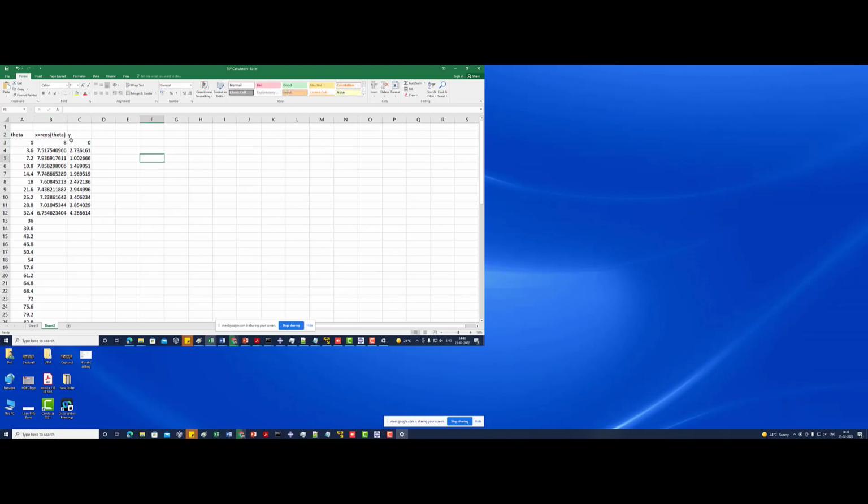So we will get the coordinates where we have to apply the boundary conditions, and then we have to calculate the values of u and v, which are the displacement in x direction and displacement in y direction. So this is simply going to be 8 into cosine of theta, but this theta has to be the radian value.